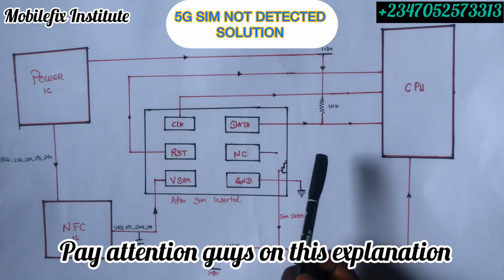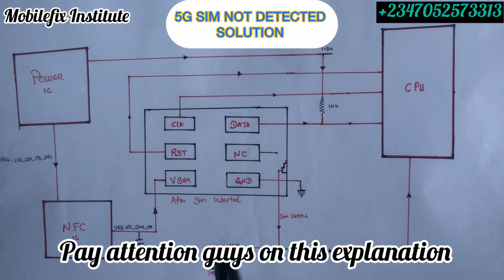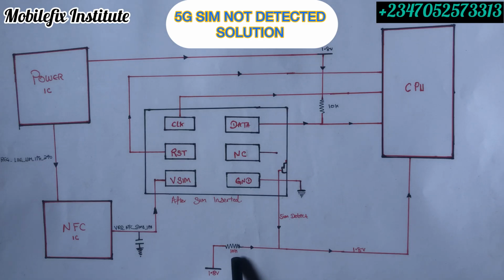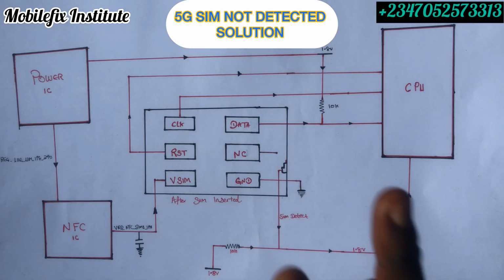You have to connect your SIM tray. Before you get voltage on this side, you must connect your SIM tray. Without connecting your SIM tray, you will get voltage on this side of the resistor. Now, if this resistor is giving you a higher or lesser value than this 10k, it's going to stop your SIM from detecting. So this value is very important. You must ensure that you test this resistor, and this resistor has to give you 10k.